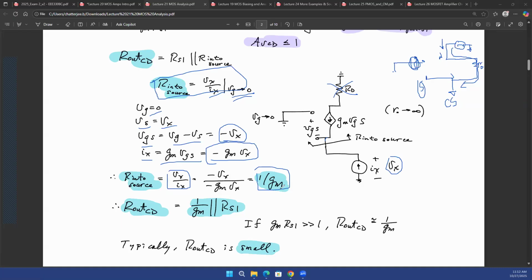Question? Say, resistance looking into... So for instance, if we have like 1 ohm resistance looking into the source node, is it equivalent to seeing a resistor connected to ground? Like when we say resistance looking into a node, it's always relative to AC ground? Yes. Yes. So again, think about that black box. If you're looking into this particular node, you're always referencing it with respect to this, which is often grounded, right? So you're talking about the resistance looking into the source node with respect to the AC ground in this case. Okay, so that's correct.